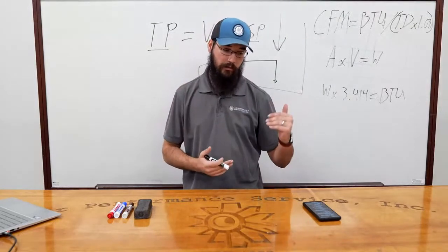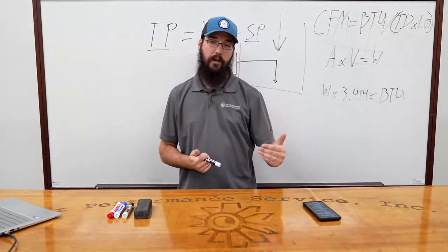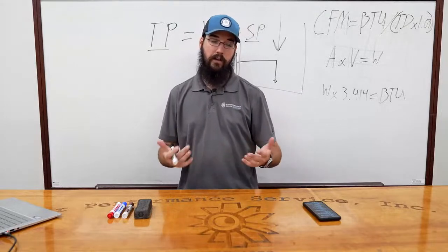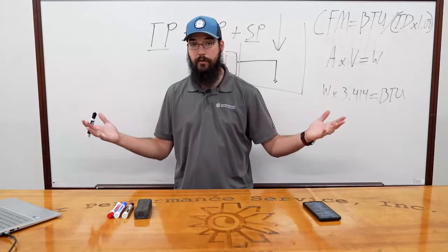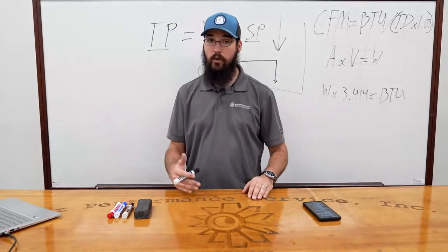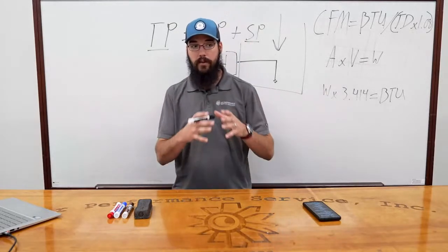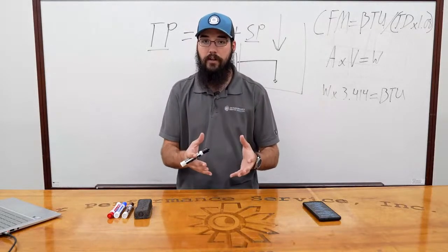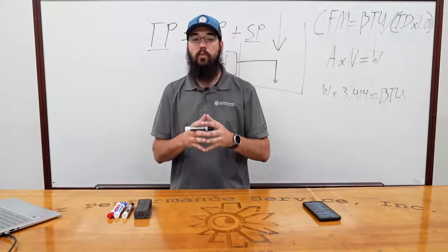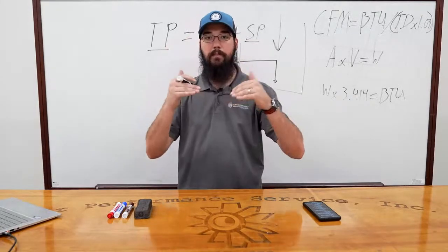And that's one of the problems with the heat rise method, that very likely you end up drying your coil out. So a wet coil, that condensate is going to restrict in its own right. And that's something you just have to be aware of.